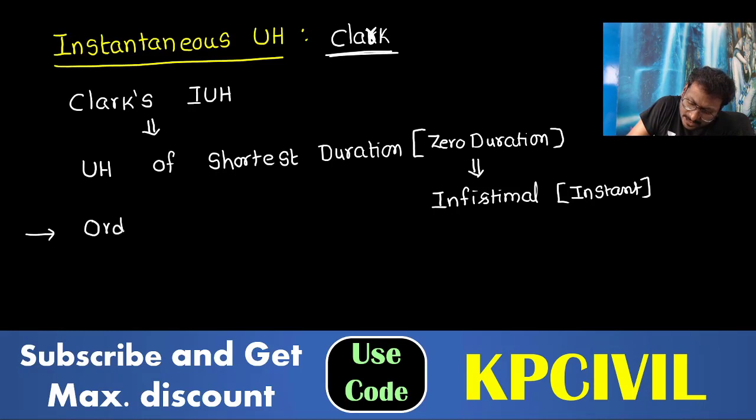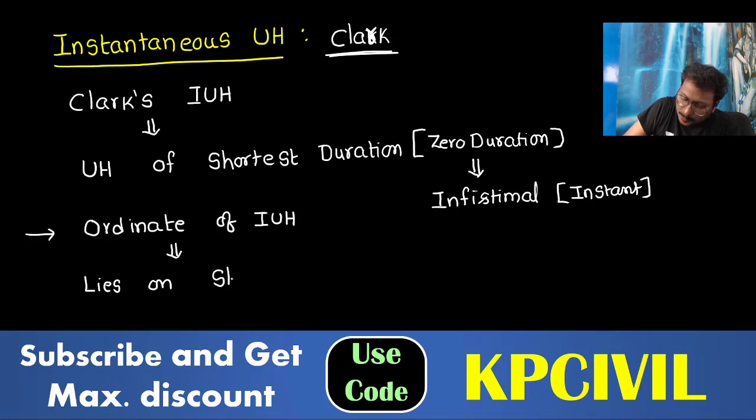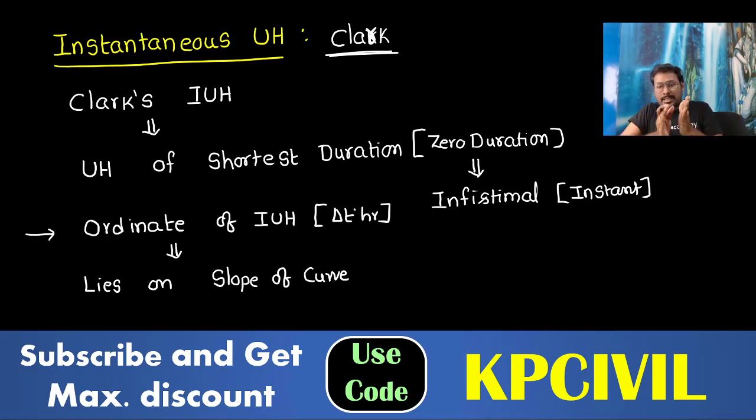Where does the ordinate of the instantaneous unit hydrograph lie? The ordinate of the instantaneous unit hydrograph lies on the slope of the S curve. Remember this. The ordinate of an instantaneous unit hydrograph of delta T hours, where delta T may be 0 also, lies on the slope of the S curve.